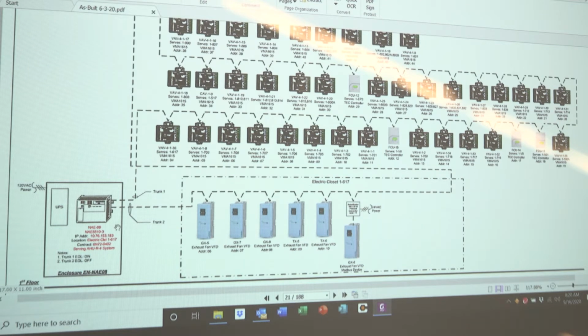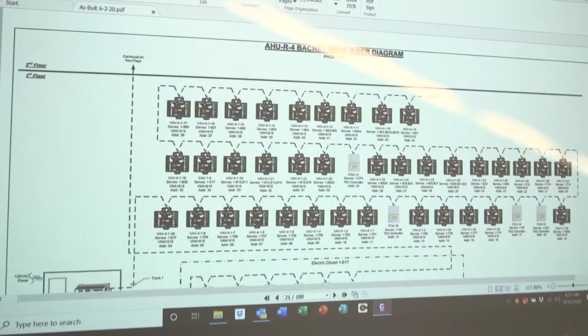Air handler unit number 4 is located on the lower setback roof on the C building. Okay, there's a series of exhaust fans that exist in this space. Okay, this is on your green roof, as well as some fans that are located in the attic space, as previously discussed. You see your communication link runs through the VFDs that are related to these exhaust fans. It runs through all of your VAV boxes and fan coil units. These fan coil units are all located at exterior entrances.